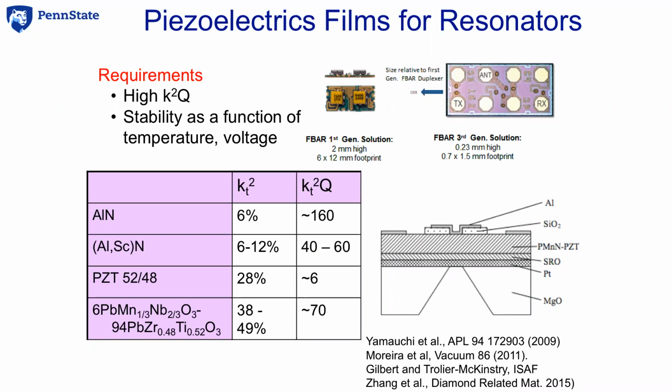So most of you are carrying around with you piezoelectric thin films in microelectromechanical systems. These are the aluminum nitride or the aluminum scandium nitride thin films that are used in the resonators that do the frequency filtering in your cellular telephone. Historically, the devices that did this frequency filtering were dielectric resonators. They were about half the size of your smallest finger. And a number of years ago, those were completely replaced with aluminum nitride, aluminum scandium nitride, or your favorite piezoelectric film, usually in a suspended structure.